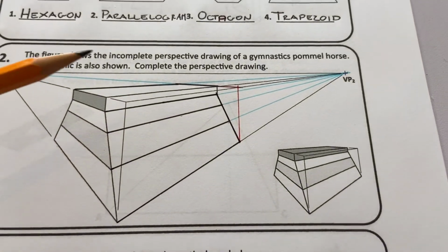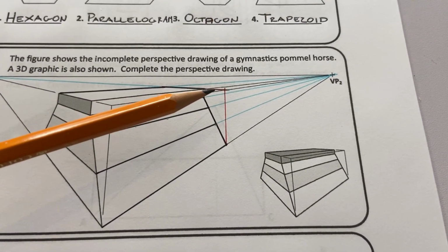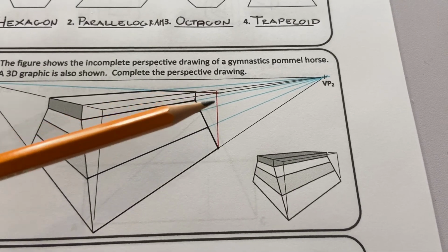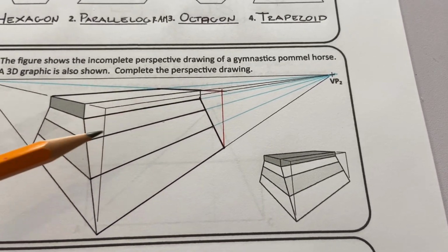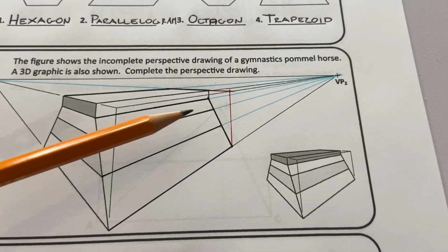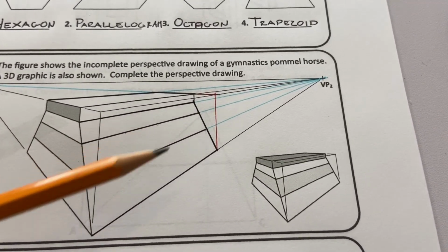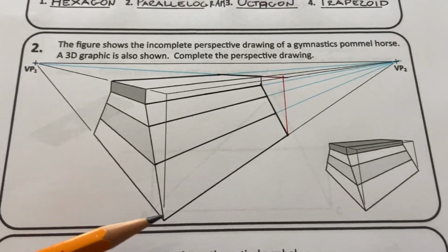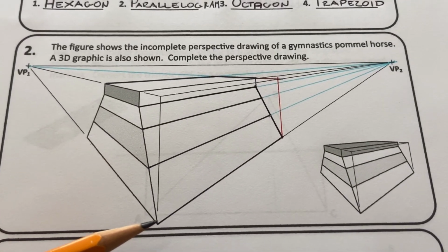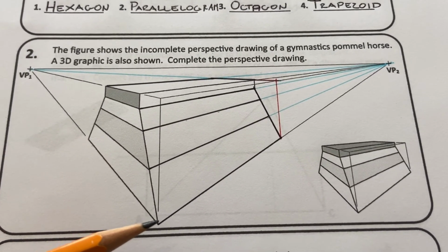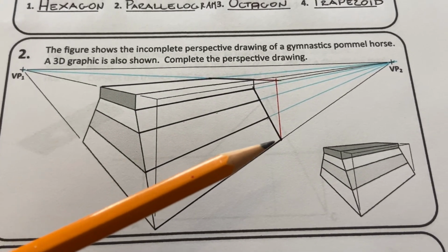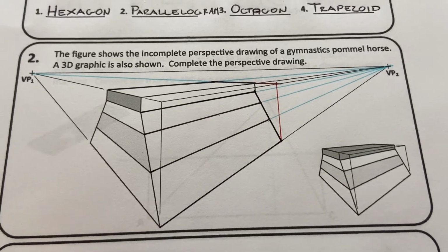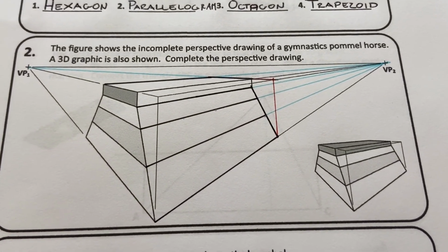So in order to locate that point, we extend out that line until it cuts this top line, drop it down, and that gives us that corner, which we now join back up to here. Then we can heavy in these lines going back into this line. Now, in the question, there's a small gap here. It is very, very important that you make sure that you heavy in all lines, because if you fail to heavy in that line there, it will result in a loss of marks.